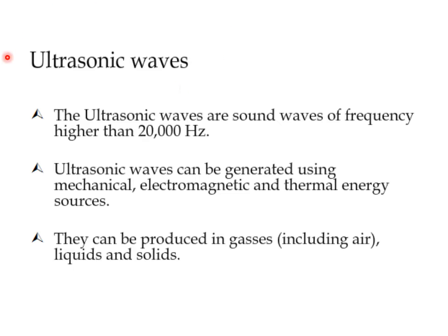Basically in ultrasonic machining, the very important parameter is to generate the ultrasonic waves or energy. So what are ultrasonic waves? Ultrasonic waves are sound waves with a frequency of more than 20 kilohertz, which is quite high, right? If I am able to produce sound waves at a frequency of more than 20,000 hertz, then they are called ultrasonic waves.